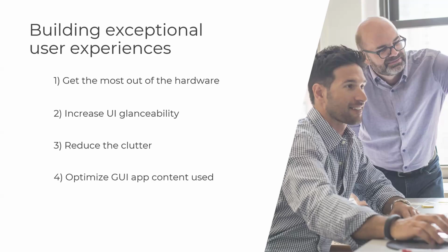Also, with differences in access time between memory types, it's generally a good idea to store the dynamic content in RAM, such as the image frame buffer, and persistent data in Flash, such as the application code. And this will really help things as well.